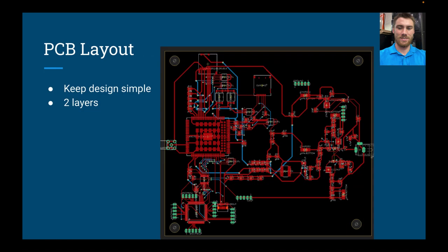As can be seen on the board layout, we chose to condense the layout as best we could and put all the voltage regulators on the right half side of the board and all the major components on the left half side of the board. This was done for organizational purposes, and we also had a 2-layer ground pour on both sides of the board to make for easier development.